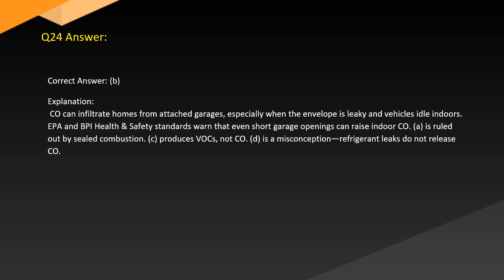Answer. Correct answer: B. Explanation: Carbon monoxide can infiltrate homes from attached garages, especially when the envelope is leaky and vehicles idle indoors. EPA and BPA health and safety standards warn that even short garage openings can raise indoor levels. A is ruled out by sealed combustion. C produces NOx, not carbon monoxide. D is a misconception. Refrigerant leaks do not release carbon monoxide.